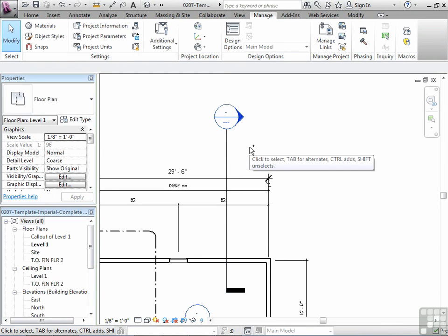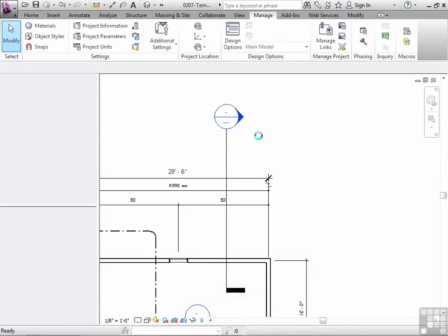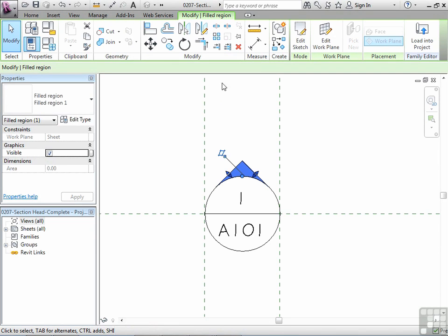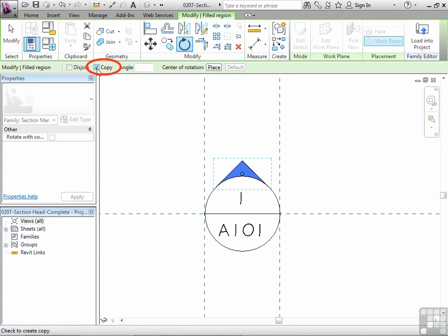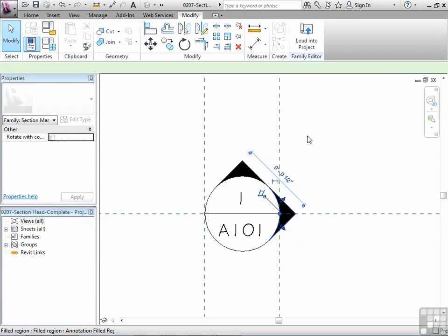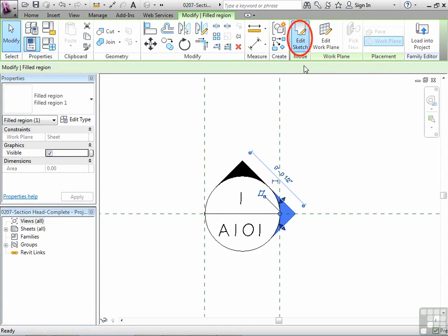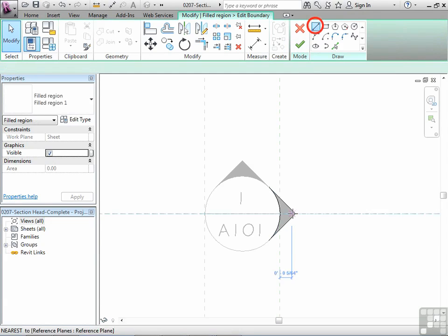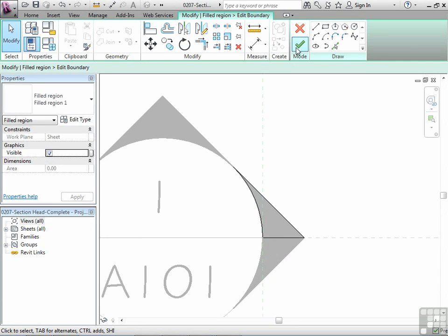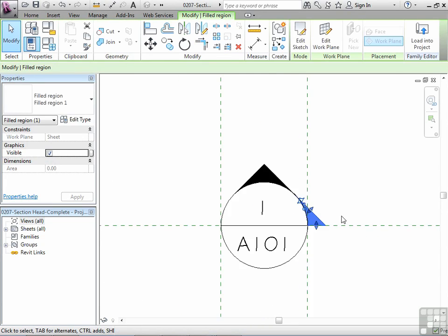Let's go in and fix this. I'm going to just do an Alt-Tab. Okay, let's pick up this, and what I'm going to do is I'm going to rotate it and copy it. Okay, so let's just move it down to there. Okay, and then we're going to click on that region, click on Edit Sketch, and draw that in. TR. Good, we just trimmed that. I'll delete that line. So we're just making it so the sketch is just that piece of it. And we can say OK to that.